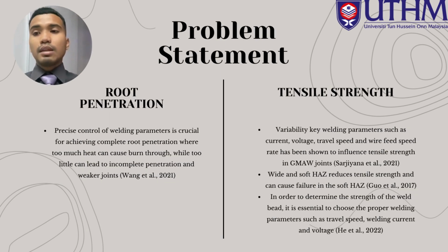For the third problem statement is the root penetration. So according to Wang et al. 2021, precise control of welding parameters is crucial for achieving complete root penetration, where too much heat can cause burn-through, while too little heat can lead to incomplete penetration and weaker joints.